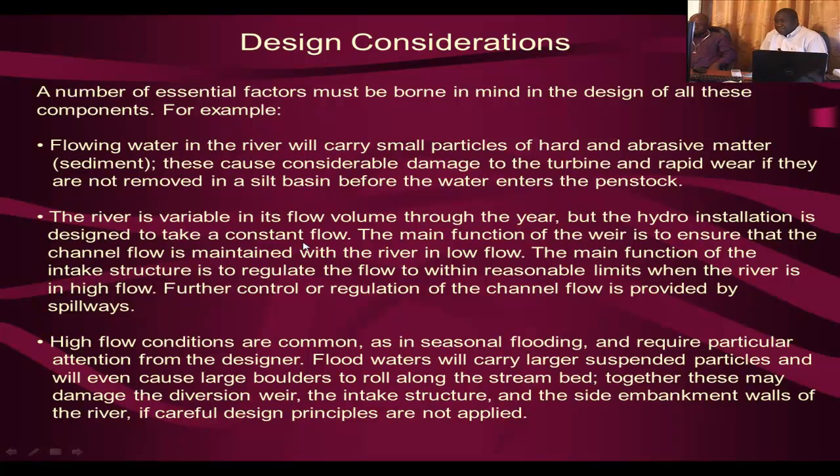3. High flow conditions are normal, as in seasonal flooding, and require particular attention from the designer. Floodwaters will carry suspended particles and will cause large boulders to go along the stream. This may damage the diversion weir, the intake structure, and the embankment walls. Care must be taken in the design of the structures.